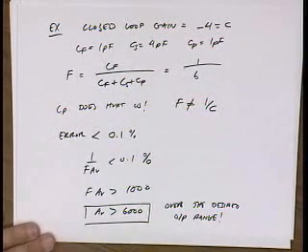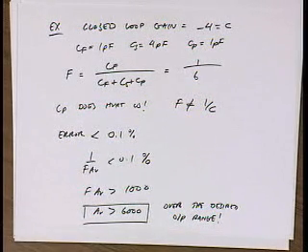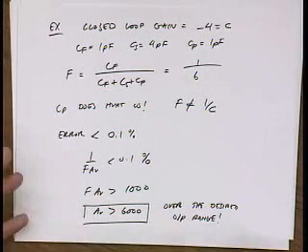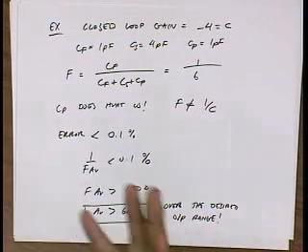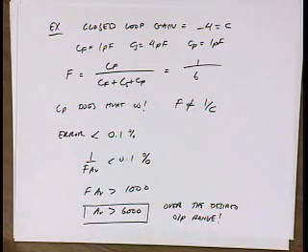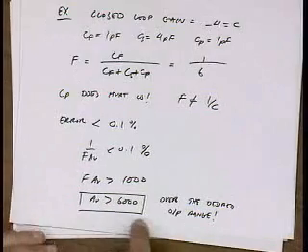Well, in the old days when you're designing with long channel transistors, gain was very easy to come by. Oh, gain a million, no problem. Nowadays, though, with short channel devices, it's pretty hard to get gain out of a single stage. The single stage gain might be 5 or 10. So to get a gain of 1,000, you're going to need a lot of stages or gain boosting. You're going to have to play some tricks. So getting gain is not easy.